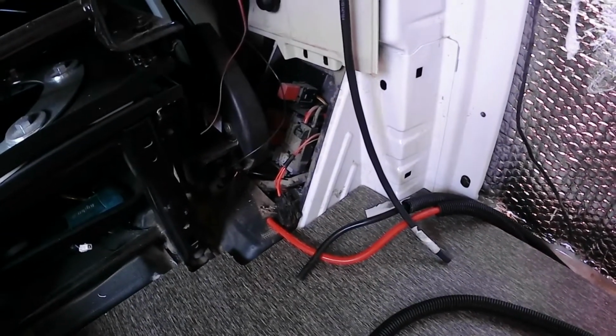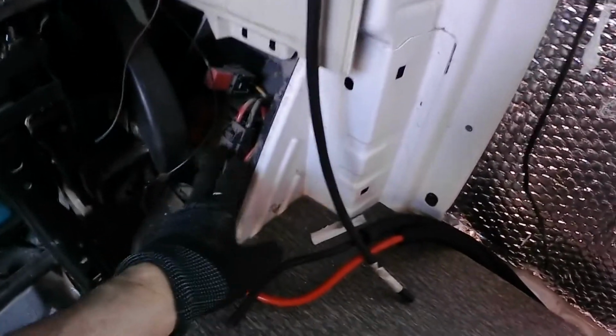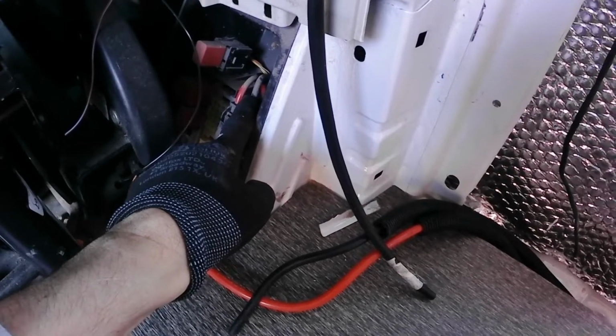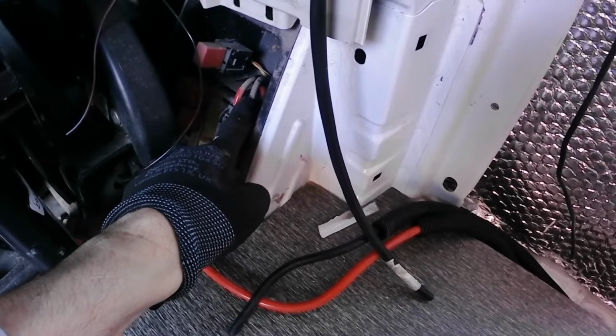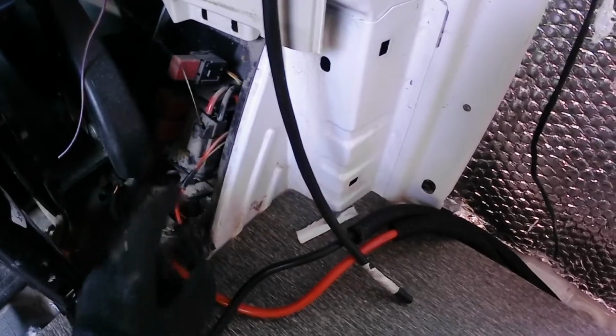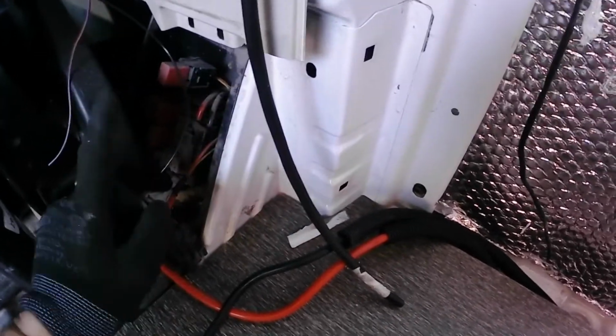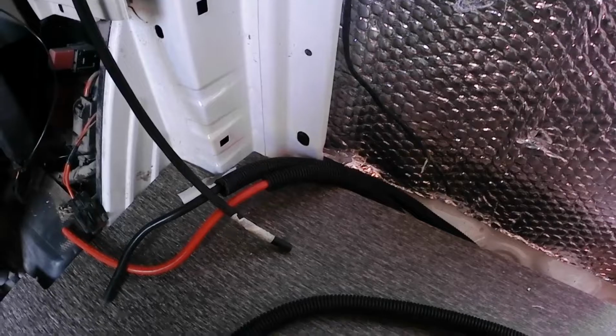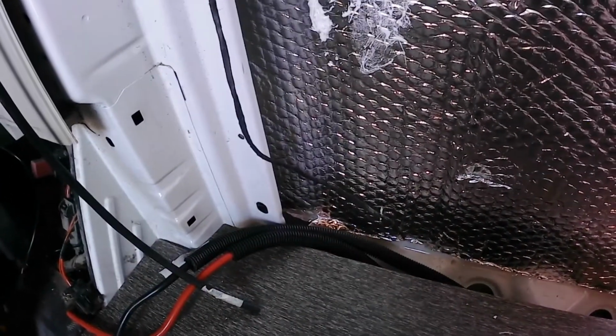This is never a big amperage, it's a small amperage. But the problem is that these thin wires are mechanically weaker than 1 mil. So usually everybody starts with 1 mil and goes up to 2 mil, 4 mil for a step or something like that, where there's bigger amperage, and that's it.